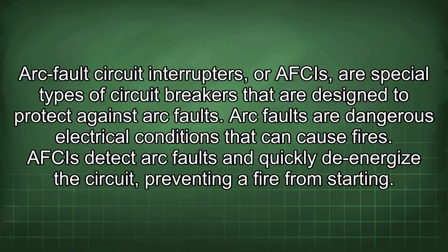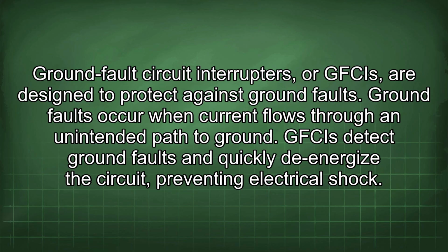Arc faults are dangerous electrical conditions that can cause fires. AFCIs detect arc faults and quickly de-energize the circuit, preventing a fire from starting. Ground fault circuit interrupters, or GFCIs, are designed to protect against ground faults. Ground faults occur when current flows through an unintended path to ground. GFCIs detect ground faults and quickly de-energize the circuit, preventing electrical shock.